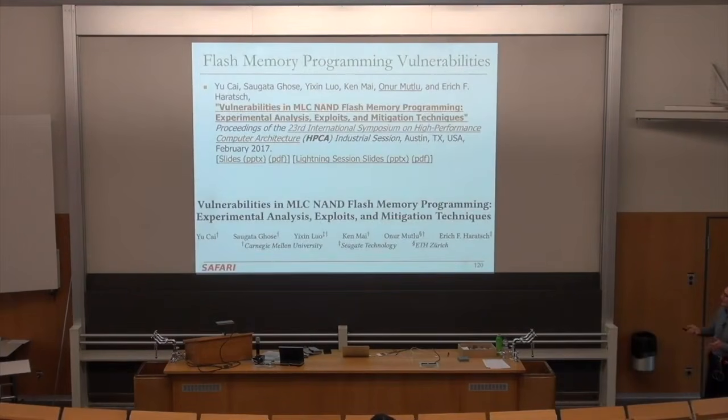So there are some other works that I'm not going to cover. This is actually interesting. This basically talks about some potential vulnerabilities in NAND flash memory and potentially exploiting them for security attacks. This is not easy, I think. Again, it's not easy because flash memory is not directly exposed to your programming language, right? You go through layers of operating system, file system calls, and then even after that, there's a controller sitting in between the requests coming from the system and how it handles those requests, right?